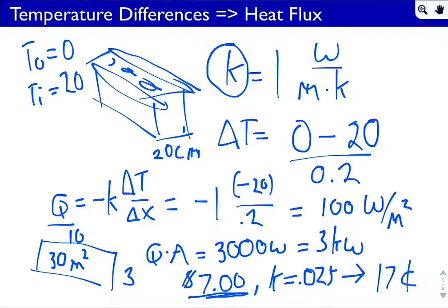Now, when you go to buy insulation materials and housing, they're often listed using this R value, which is related to K. R is essentially the heat resistance or thermal resistance. And I think what they do is basically say for a given temperature gradient, what is the heat flux through this material? So wrapped up in that is the thickness of the material. You'll see R values listed for insulation. It's kind of like an inverse conductivity. It's a resistance such that the larger your R value, the better. Whereas with conductivity, the larger the K, the worse, if your goal is to reduce heat losses.